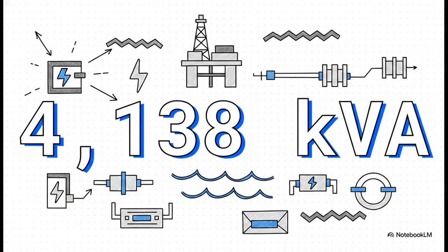Next up, we take that 3,600 kilowatts and divide it by our assumed low-voltage power factor of 0.87. We punch that in, and that yields exactly 4,138 kVA of required generation. That right there is the absolute minimum size of our power plant just to run the daily operations.